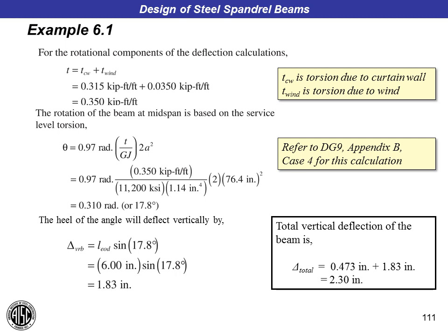All right. So we'll do one last question here, and it sort of ties in with what you were just talking about. Given this result that you show here in example 6.1, the question is, in your practice, do you typically go for shorter torsional spans rather than trying to make spandrel beams span their full, say, 30-foot length, or do you ever try to make those 30-foot lengths work for a torsional span?